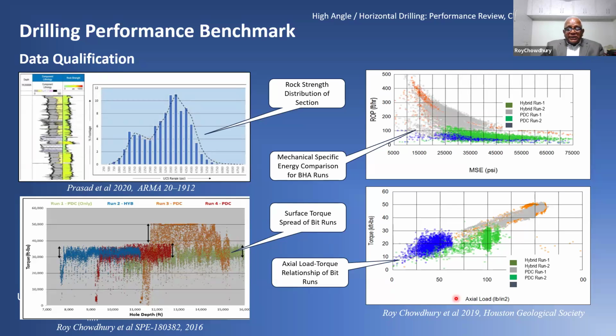In those cases, you need to be able to normalize those readings and see what kind of force, or weight on bit per unit area, has been used. And the slope of this curve, for everybody's ease of understanding, is called the aggressiveness of the bit.